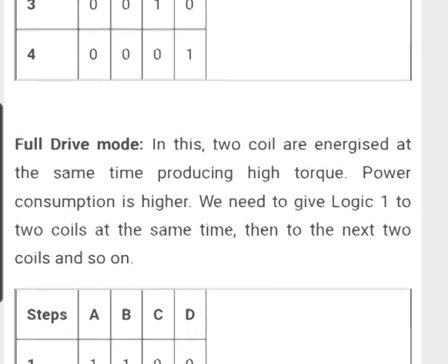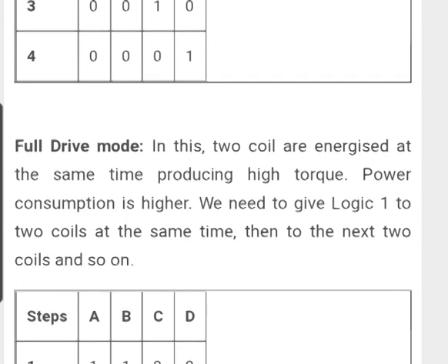Now what is full drive mode? In this mode, the 2 coils are energized at the same time, producing high torque, and power consumption is higher. So we need to give a logic 1 to the 2 coils at the same time.